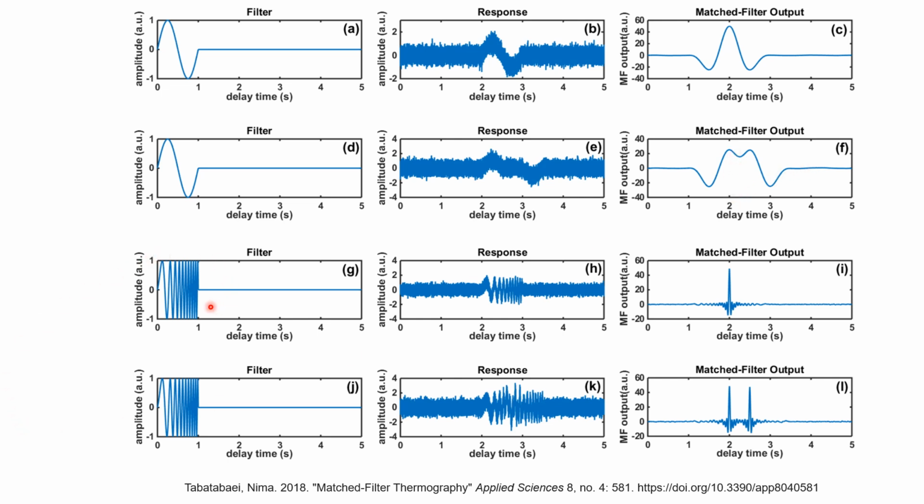Similarly, here we have another signal, which is a kind of frequency shift. It changes frequency. This is the waveform that we select. If it is buried in noise, we get something like this. It's not easy to make a decision where exactly is the output and how many of them do we have. So once we do correlation, once we go through the matched filter, the output tells you exactly where the signal is in time, the maximum value.